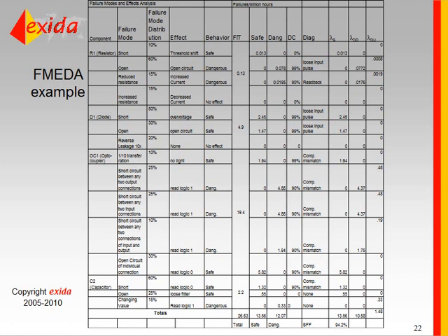Okay, and then what you need to do is once you've identified the failure modes for each component, you need to identify what is the effect of that failure in this specific circuit. Is it going to cause a shutdown? Is it going to cause a loss of the safety function, or what have you? So the effect kind of describes specifically what it does in the circuit, and then the behavior can either then be safe, dangerous, or no effect.